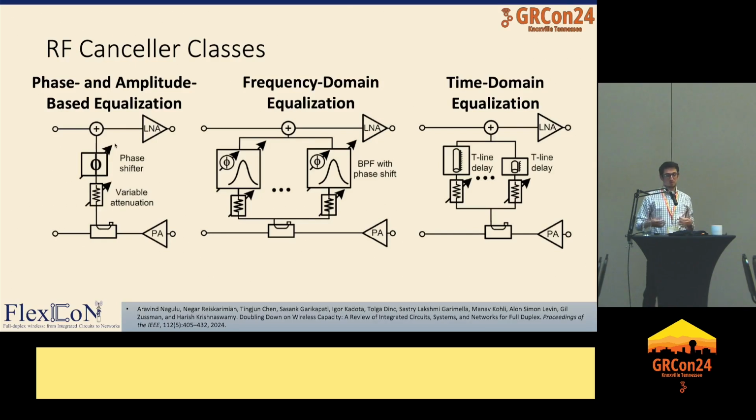Next step was to explore frequency domain equalization, where essentially you have banks of passband filters, which again, you can play with a bunch of different configurable settings there. And finally, time domain equalization, which applies the same principle as before with the phase and amplitude-based equalization, except instead of explicitly modifying the phase, you are trying to emulate the delays that the self-interference travels through. And essentially, again, your goal is to have as much destructive interference as possible.